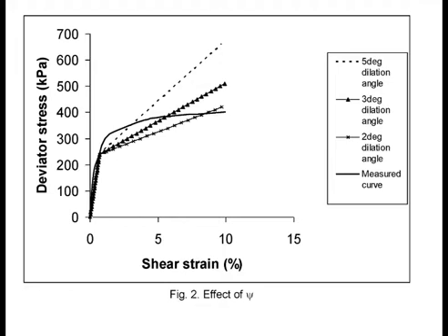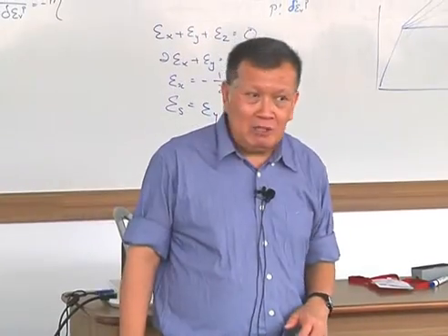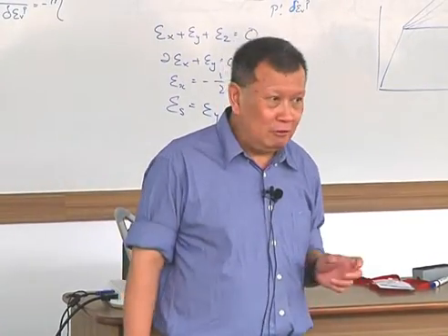Now, if you take this to be the U point, then you cannot use this as the Young's modulus, because then you'll shoot the curve right up to here, the elastic portion, which is wrong. If you want to take this to be the U point, you want to say my elastic portion is down here, which is conservative. You know what I mean? And so your Young's modulus will correspondingly drop. So it's not necessarily more optimal. Okay? But ultimately, which one will save you money? There's something you have to try.